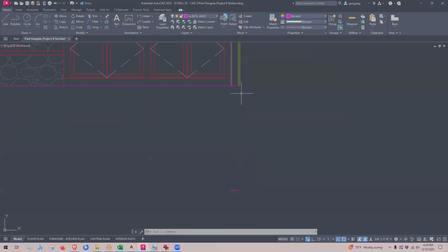So that marks the very bottom of our footing. And remember, the foundation wall will go on top of it. And the height of our footing is 8 inches, so I'm going to offset 8 inches up. So this will be the footing down here. This is just the bare bones of it. And then the foundation wall is going to come down like that.